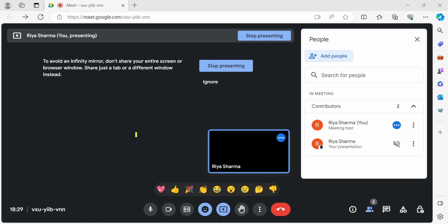So delta U equals Q plus W. If you take W to this side, it will be delta U minus Q. In this step you are getting it. If you solve it, it's minus 12 minus 8, which is equal to minus 20 kilojoule. This is the solution for our problem, where we have been given Q. So write what has been given: Q equals 8 kilojoule, and delta U equals minus 12 kilojoule.